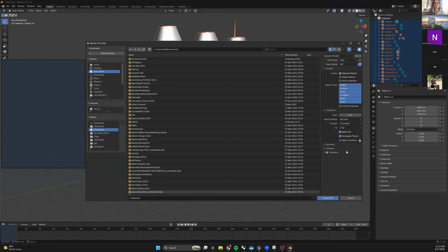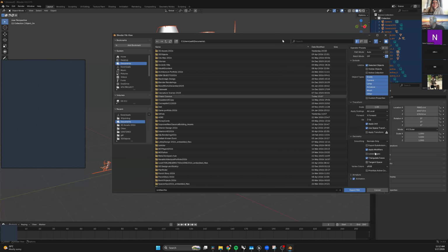That way I know that my 3D software, my object, and Unreal Engine are coordinated on what's up, what's down, and so on. Also, click on the geometry and make sure you have triangulated the faces so the computer can actually make the calculation. Give it a name.